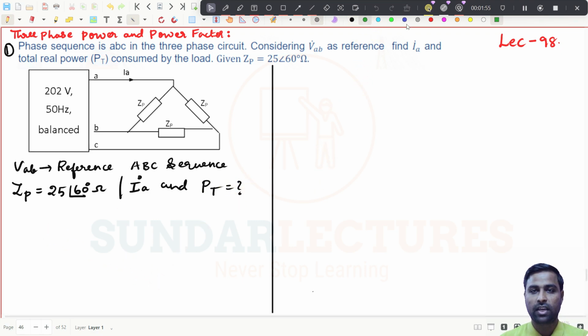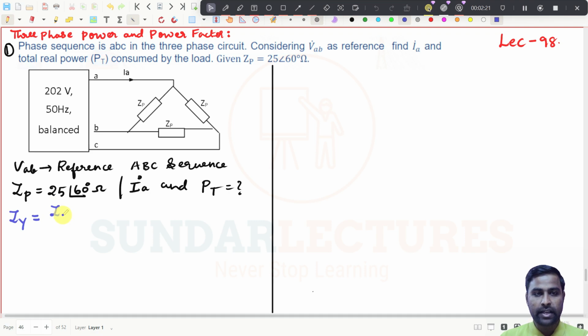Now they have given you the delta connection. What I will do is try to convert that into star. For the star connection, I am going to change this delta connected impedance to star, then it will be ZY equals Z delta divided by 3.